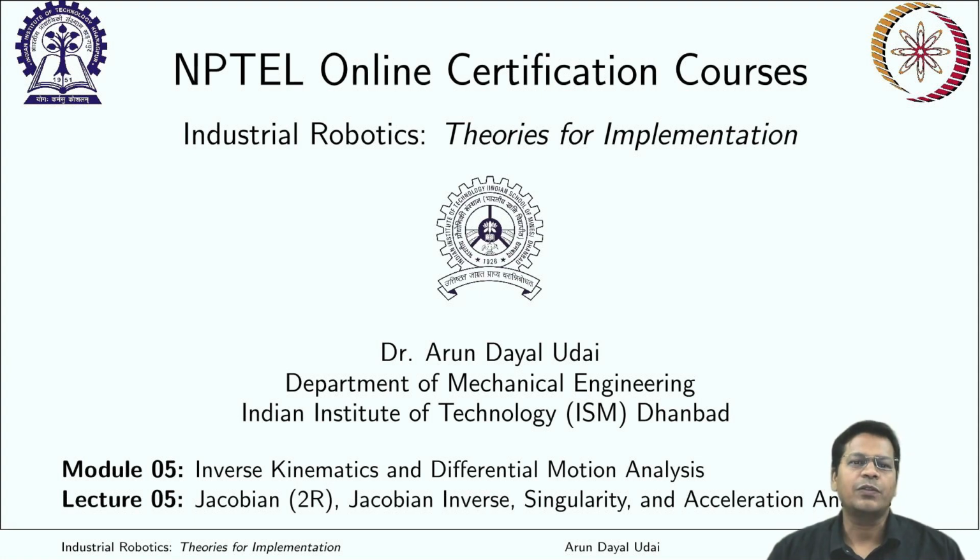Everyone. In the last class we discussed the Jacobian that relates the joint rates to the end effector rates. We saw how a Jacobian can be calculated for a 2-DOF planar arm. We also saw the vector matrix approach for calculating the Jacobian of a general n degrees of freedom robotic arm. Moving ahead, today we'll discuss the general Jacobian formulation further, and we'll do the Jacobian for a 2-DOF manipulator using the vector matrix approach. We'll understand what the singularity of a robot is, and we'll also do acceleration analysis.